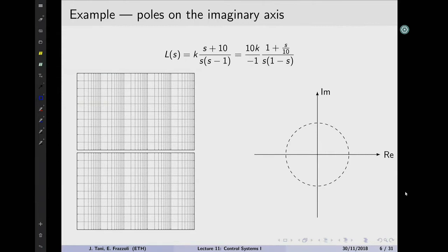So the first thing we want to do is recast the transfer function in the Bode form, right? So we want to make each one of those terms be the same as what we analyzed, having in particular the form, for example, of 1 plus tau s in these binomial terms. Here, I'm being a little bit exaggerated with the notations just to show the passages that I'm doing. The first part is the numerator. Well, we have to take a 10 out of it, and here it is.